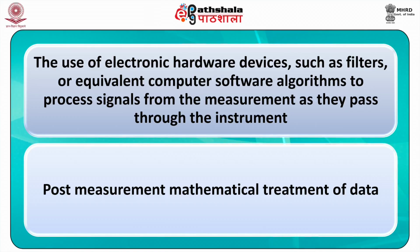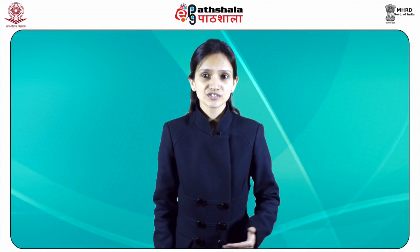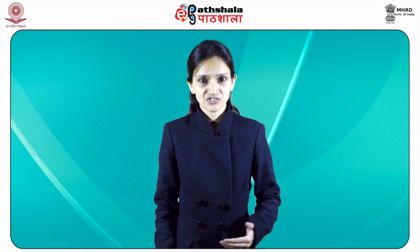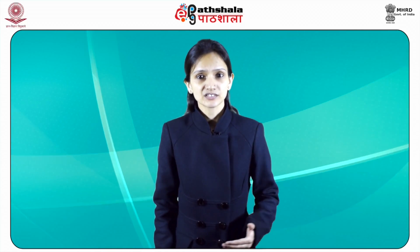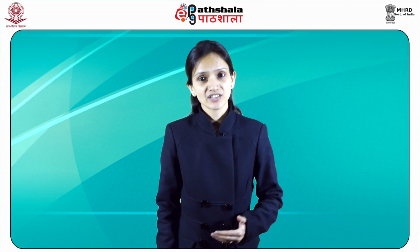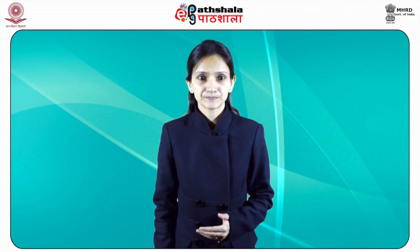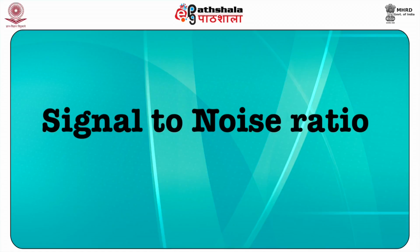Among the more useful post-measurement methods are statistical techniques. In addition to signal enhancement, these techniques aid in identifying sources of error and determining precision, while providing a method for an objective comparison of results. This module will deal with some common noise reduction techniques and briefly review important statistical methods typically used in the treatment of instrumental data. First, signal to noise ratio.